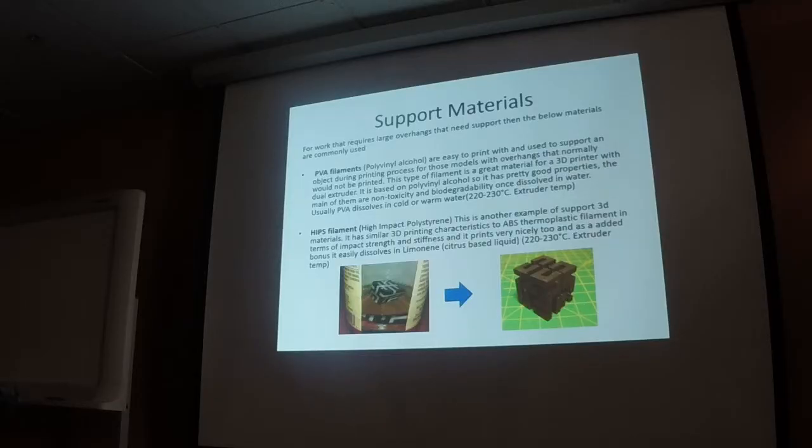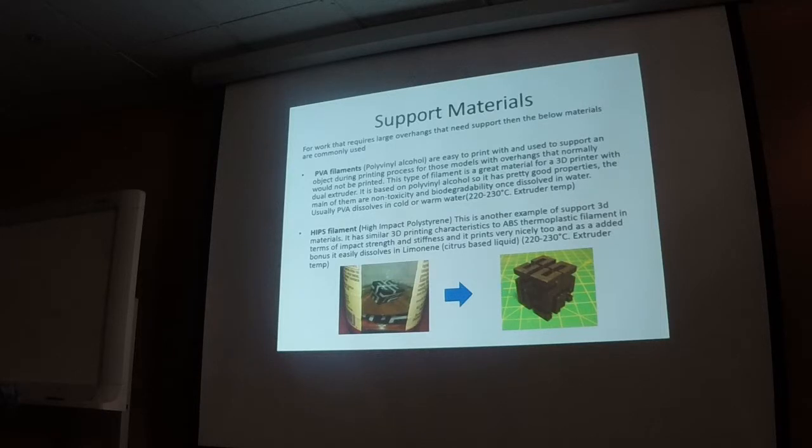Because a lot of times with a single head extruder, if you're going to use support material, what you have to then do is break off the support material and then clean the face up that had that support material. So using this on a dual head extruding system is much better. As you can sort of see in the picture below, the support material there is in that box in water, and that's how it dissolves, and you end up with a clear, empty kind of shape in it. So it allows you a lot of ways to be able to do what you need to do.